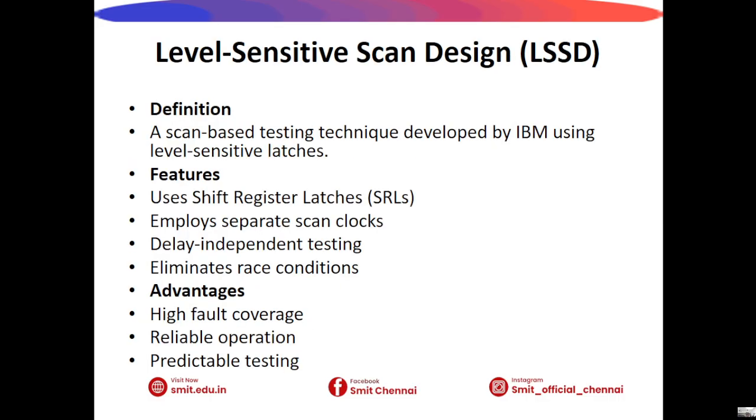Next, we see about the level sensitive scan design. LSSD was first developed by IBM as a reliable scan testing methodology. It uses level sensitive latches instead of conventional flip-flops. Separate scan clocks and system clocks ensure predictable operation. One major advantage of LSSD is that it eliminates race conditions and timing hazards, making testing independent of circuit delays.